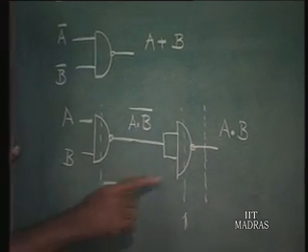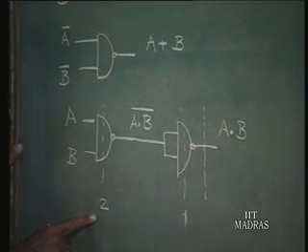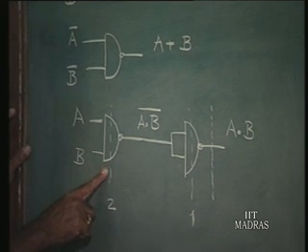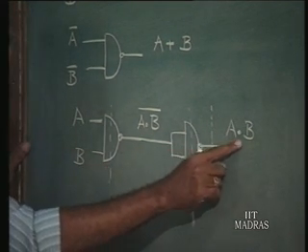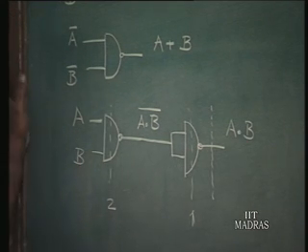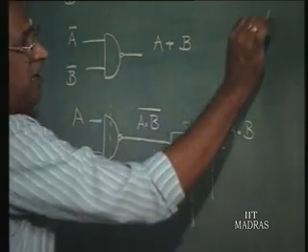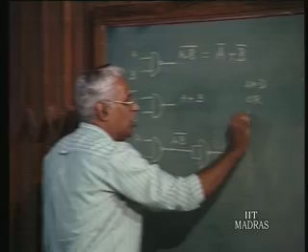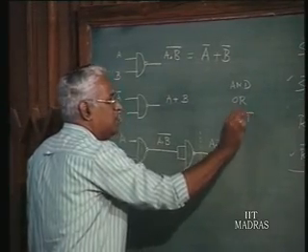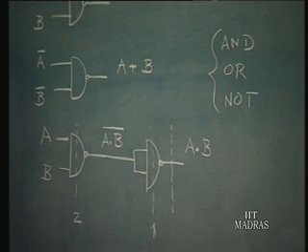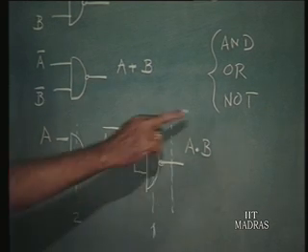So, that particular NAND gate, which is two levels away, works like an AND gate with its inputs true. Fine. Now, you know that using AND or AND NOT, you can synthesize all the logic functions that you need.